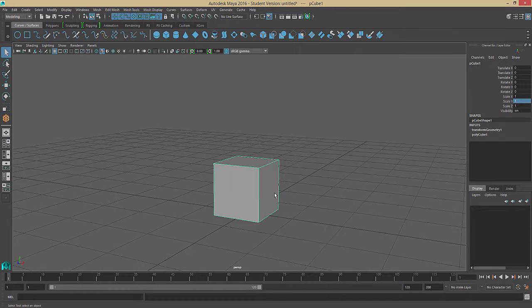The other thing we want to look at is different view modes within Maya. Now if we hit our 4 key in Maya, so the number 4, we're looking at the wireframe. You'll notice that when I hit 4, it lit up this little box in the viewport here. So we can turn that box on and off and you'll see it's jumping back and forth from wireframe to shaded. So 4 is just the shortcut. 5 will be the shaded mode, so just the number 5 on your keyboard is shaded mode, the number 4 on your keyboard is wireframe mode. And that can come in handy when you're trying to get vertices and edges in the back of your cube.